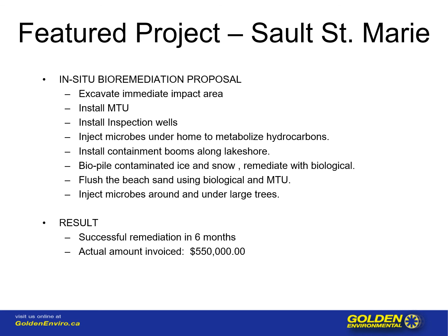This was an in-situ bioremediation plan, which involved excavating the immediate impact area. Again, excavating the immediate impact area slows down any further migration of the oil, but you do not excavate to the point where you compromise the building. Then when we installed a mobile treatment unit, we installed inspection wells so we could monitor the movement. This property was right along the shore of Lake Superior, and inspection wells were necessary in order to monitor any migration of oil or microbe amendment.